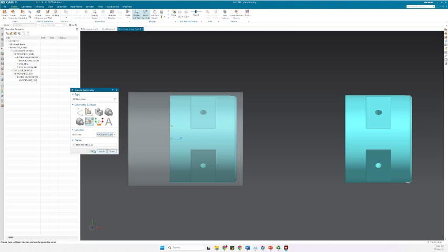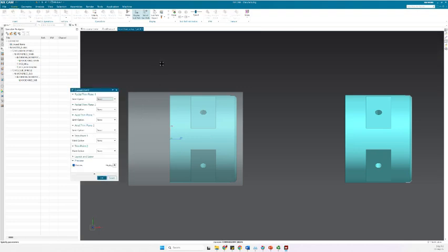After that, I click here, and now I need to define a plane similar to the PowerPoint that I showed you, a plane parallel to the ZX plane. So it will be axial plane trim 1. I could define a point, I could define a distance.